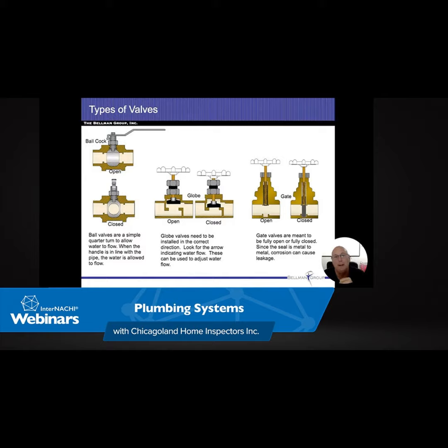Black iron is typically used for gas pipes. We really don't want to be using iron. It rusts, it corrodes, it's pretty bad. I've seen this rarely on galvanized homes. Somebody must have had a leak, or maybe it was corroded real bad and they replaced a section of the galvanized pipe. They didn't know better, so they purchased black iron fittings and black iron pipes, and since everything's screwed together because it's the same pipe thread, they figured that it was okay, when really it isn't.